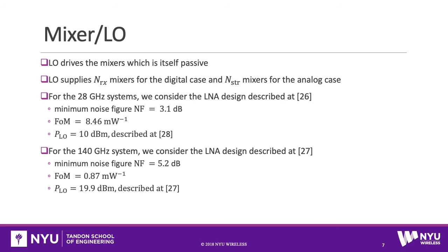In the two systems that we analyze at 28 GHz, we considered an LNA with a noise figure of 3.1 dB and an LO power of 10 dBm. For the 140 GHz system, the LNA has an almost 10 times worse noise figure and a much higher LO power.